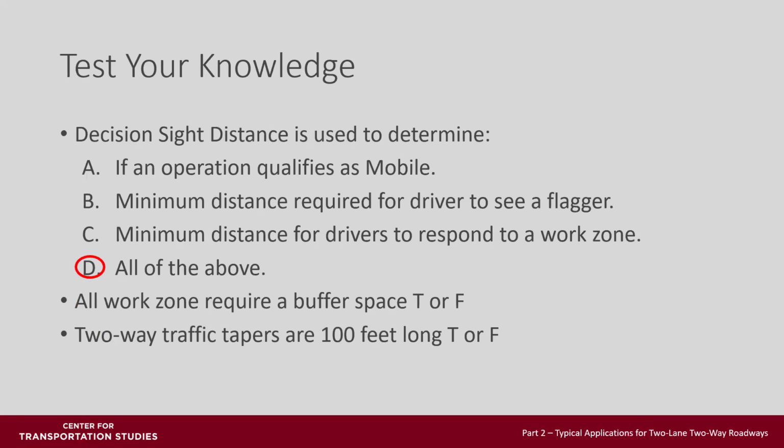All work zones require a buffer space. True or false? False. It's not always necessary or possible to get a buffer space, but it's suggested that they be used whenever possible. Two-way traffic tapers are 100 feet long? That's false. All two-way traffic tapers are 50 feet long.